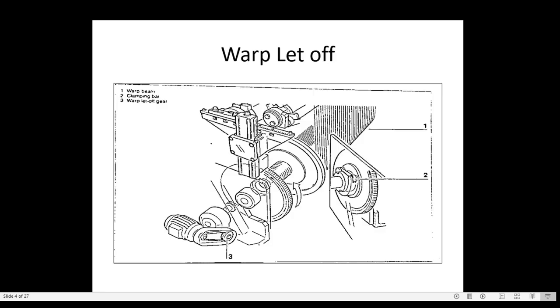So in the control panel we can add the PPI, and the same PPI signal will go to the let-off motor, and the let-off motor will accordingly release the warp, and accordingly the take-up of the fabric will be taken. So the signal goes to both let-off and take-up when we insert the pick PPI in the control panel. So this is the unique feature of this let-off.